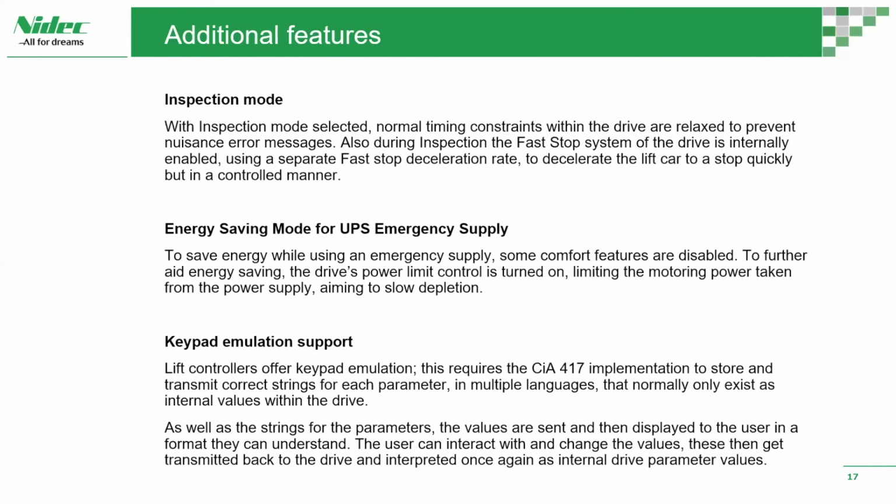But for 417 to be able to implement the keypad emulation on the lift controller, the 417 implementation in the drive actually stores and transmits all the correct strings for each parameter and in multiple languages, such as German or English, which normally exists only as internal values within the drive. And as well as the strings to the parameters, the values are sent and then displayed to the user on the virtual keypad. And then the user can interact with these and change the values, and these then get sent back to the drive where it's interpreted once again as internal drive parameter values and set as such.